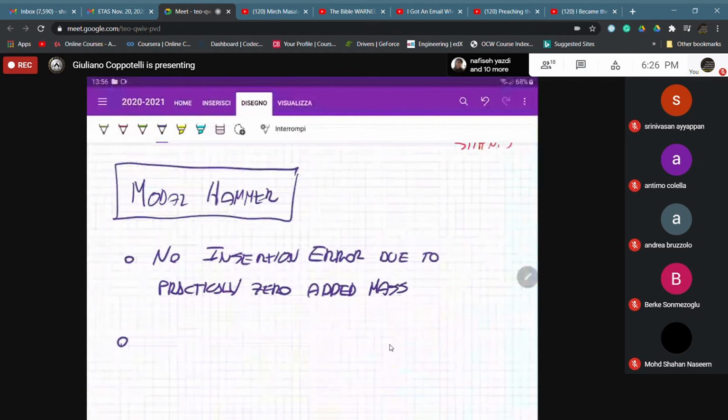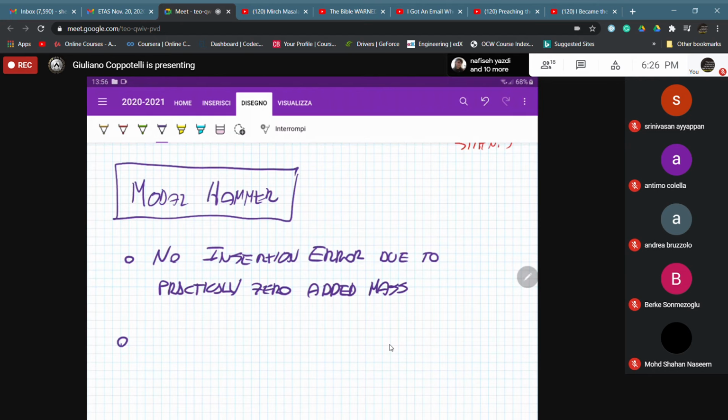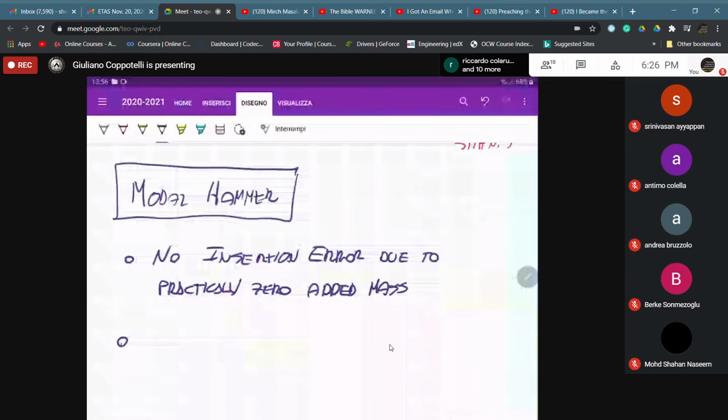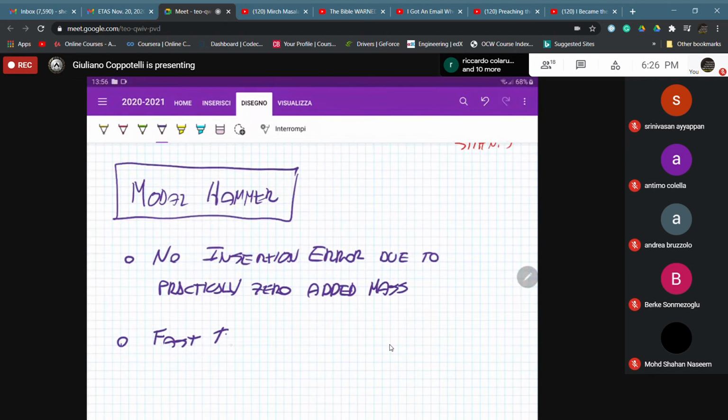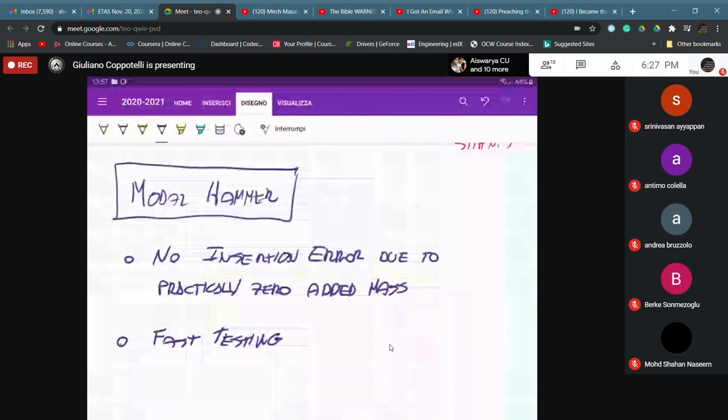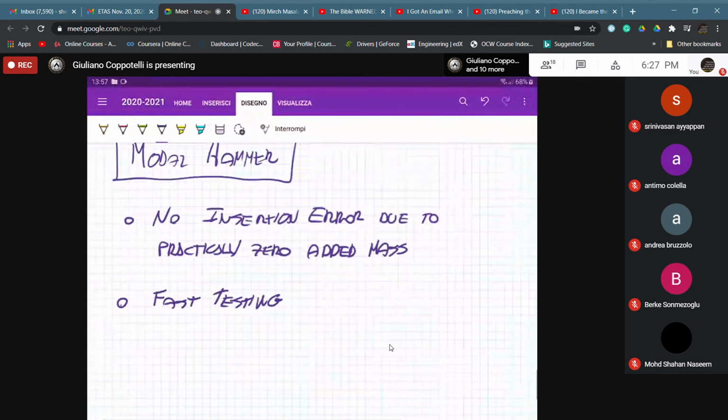It is very useful because by using the modal hammer, we can have a very fast testing. We do not have to make all the connections, all the cablings required to set up the shaker measuring chain. Then we can also say that by using the modal hammer, we are having a broadband excitation with a short excitation time. And that is one of the most advantages of that.